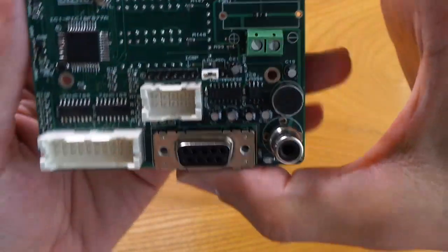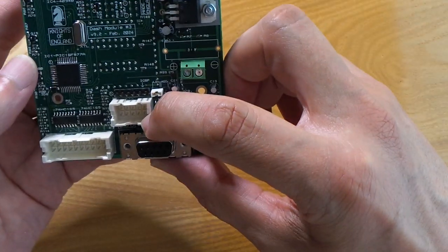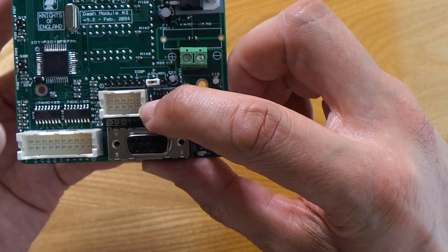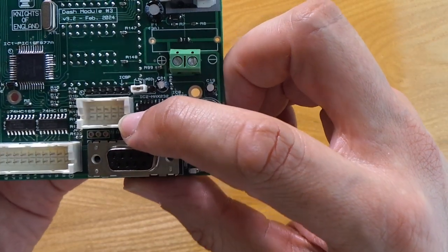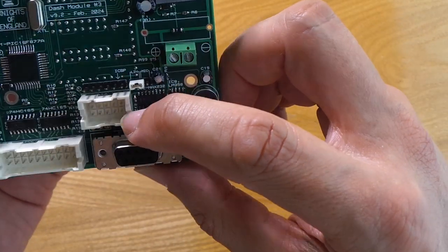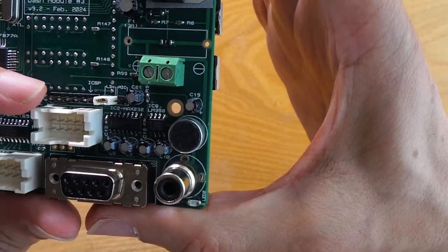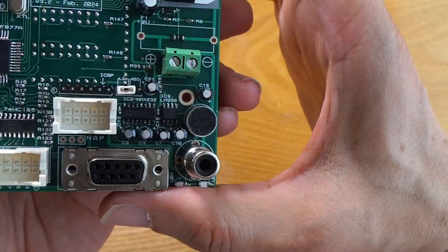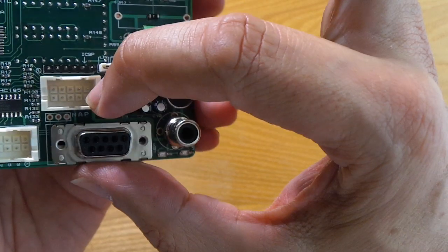We have two what are called JST type connectors on the unit. One is a 10-way connector here, and one is a 20-way connector here. Now the 10-way connector is going to be common, i.e. the same on all version 9 dash modules, and it has a pinout which will be the same across all modules. So let's go through the pinout for this unit, because this is the one that you'll really need to connect.